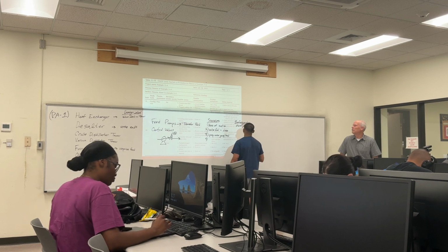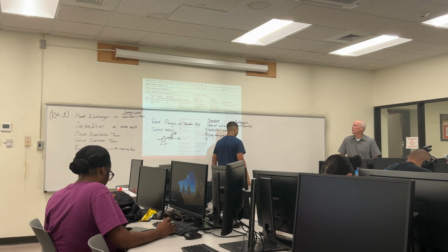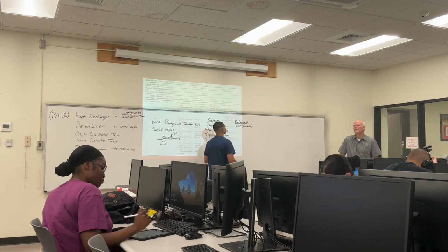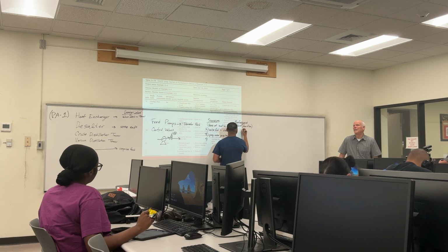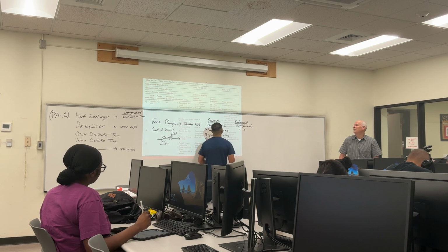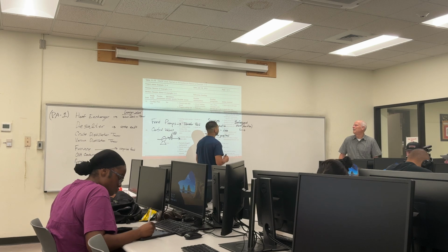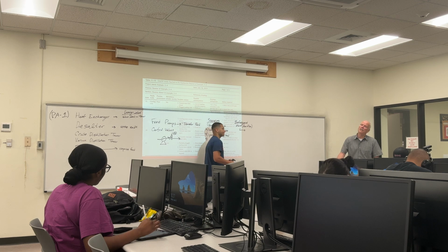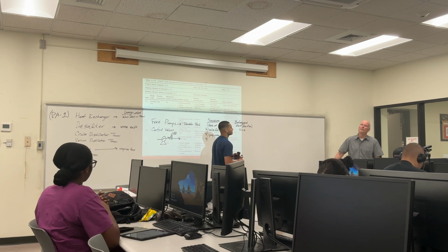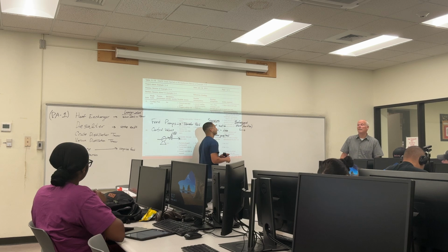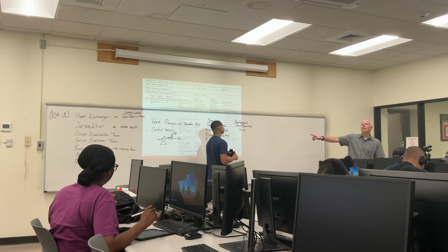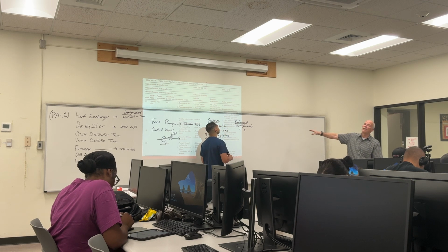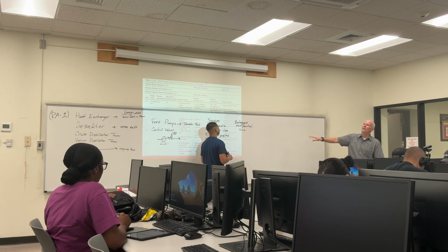And then what's the action that was required? Make the valve fail open? Maybe, but that doesn't sound like very good. I feel like that could lead to further issues. If you lose flow, that's the question. What is the action you take? Not saying we're going to interrupt the scenario anywhere. You can do a safeguard. You were saying safeguard, make the valve fail open, that's fine. You can put that under safeguard. But I was saying, what's the action that's required if you lost flow?